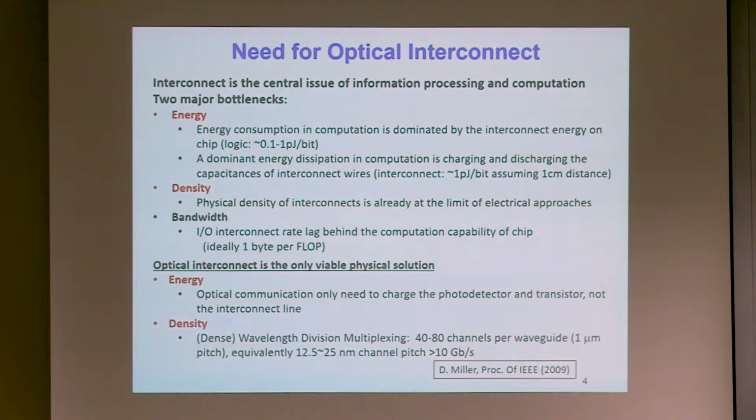For example, in terms of energy, the electrical interconnect energy is getting too high, and photonics has the potential to address that. Further, and important, is simply the physical density. In your IC, you eventually run out of physical space for the pins to drive data in and out as your data rate starts to increase, because every pin can only carry that much data rate and you just need more pins. In reality, more than half of the pins on your chip are simply carrying DC power to supply the transistors inside. So therefore, you want a much larger so-called density.